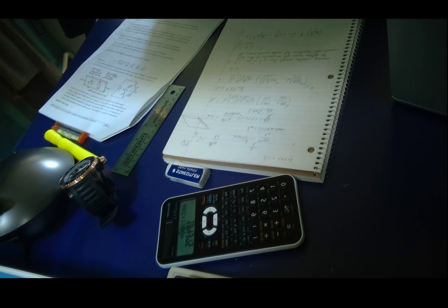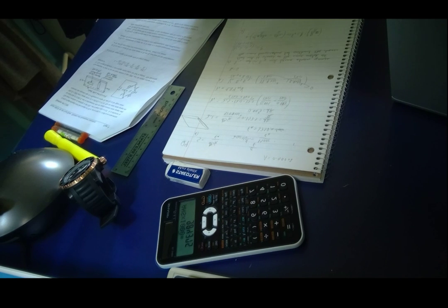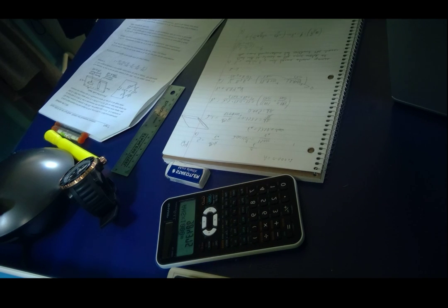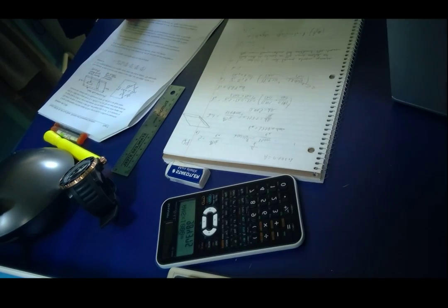Now, there is nothing being said about the capacity of the strain gauges to be able to feel not transverse, but perpendicular strains. So we'll assume that the strain gauges only experience strain in the direction they are parallel to. That means that we need to find epsilon t, but that's where the fun comes in.